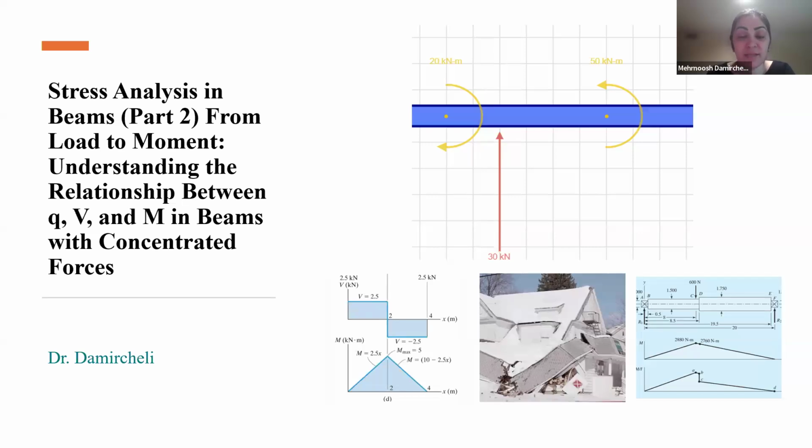The goal is to understand how shear force V and bending moment M vary along a beam, meaning the shear force and bending moment diagram, and how they are related to the external load Q as a function of X. We will use the cut method and equilibrium equations to determine internal forces, and we will explore how concentrated loads or moments cause discontinuities in the shear and moment diagrams.